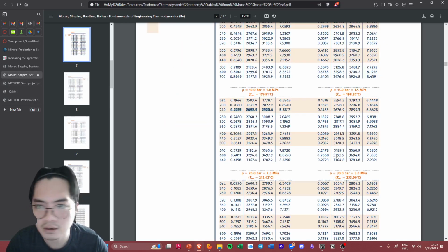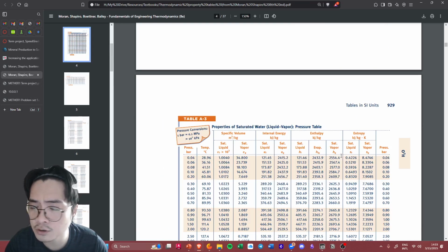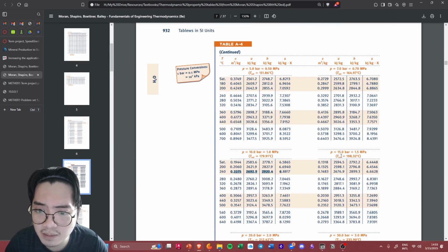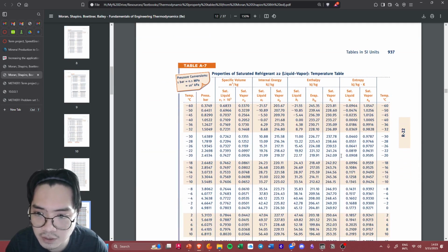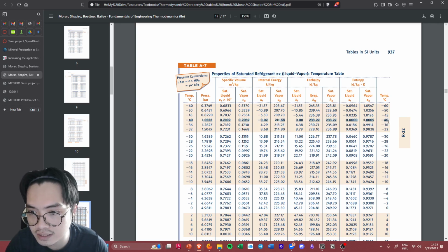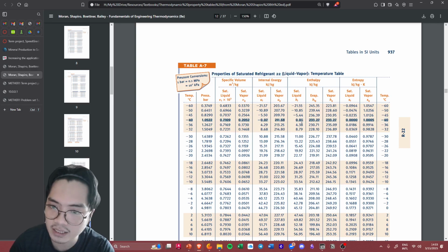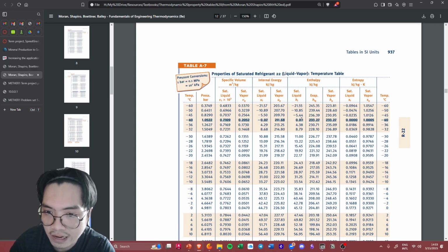in your Steam table, I think it was R22. There is a reference point in here. Look, if you see R22 at negative 40 degrees Celsius, you will see that it is oddly all 0 for H and 0 for S, for entropy.